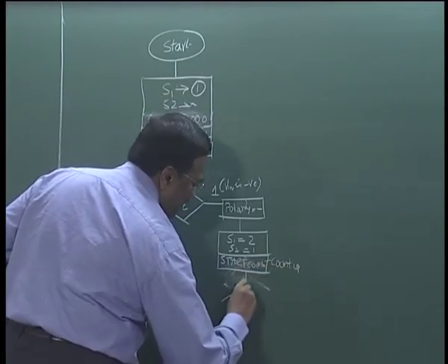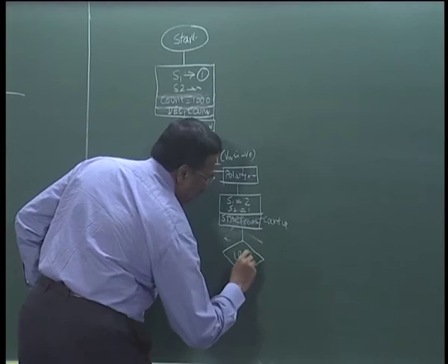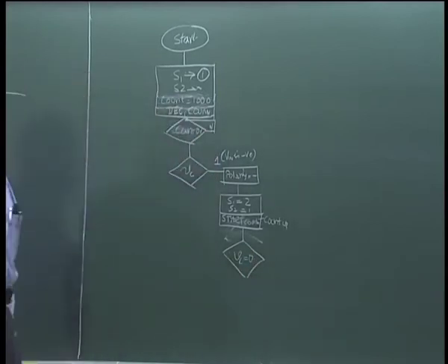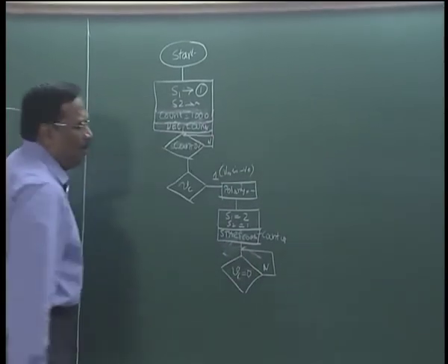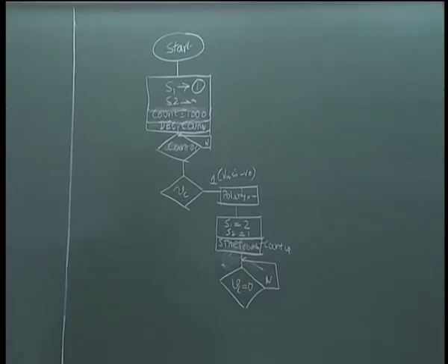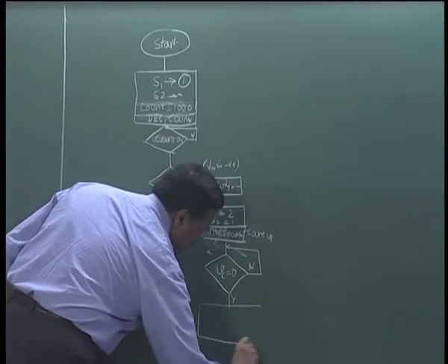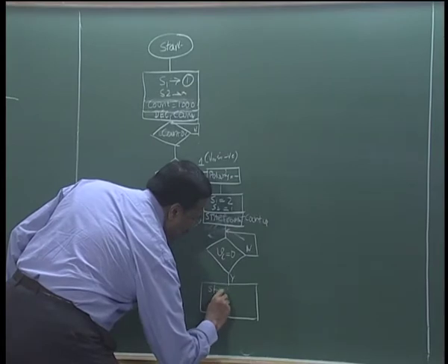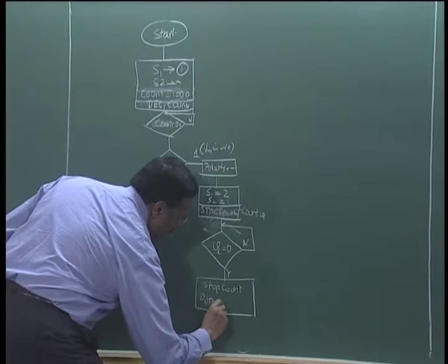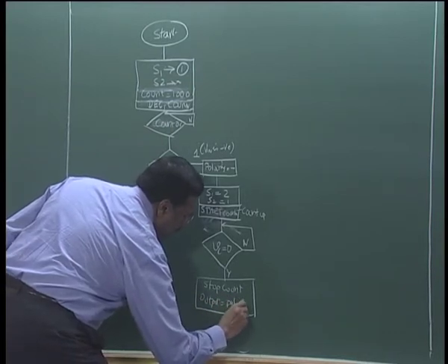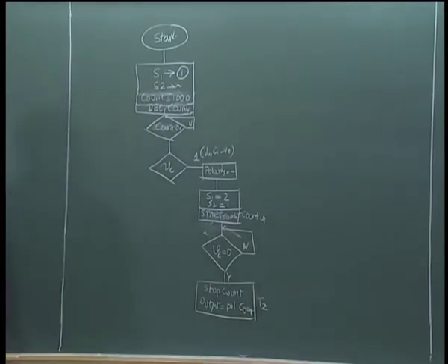Then we check whether the comparator output voltage is 0, right. If it is no, we continue waiting, the count will keep on counting. When it is yes, we say stop count, output is equal to polarity and count. So, this actually measures T2 with polarity, right.